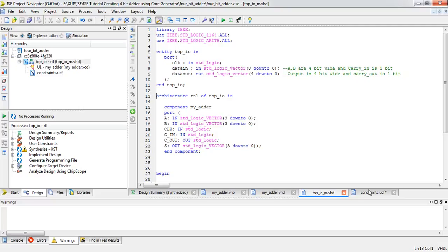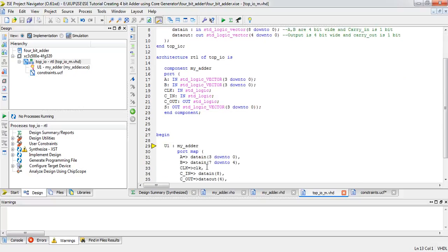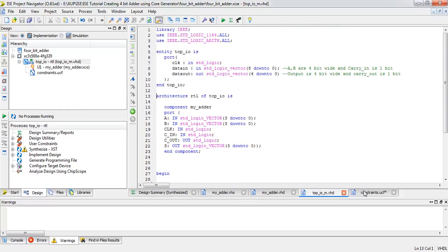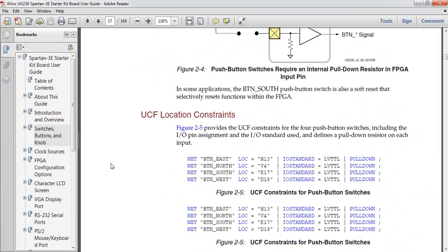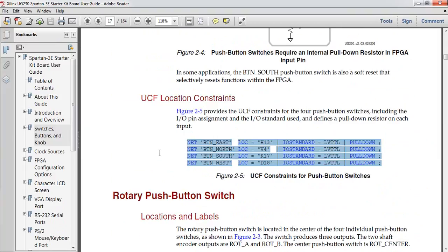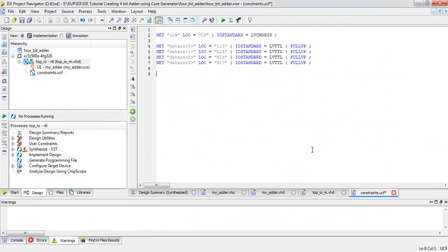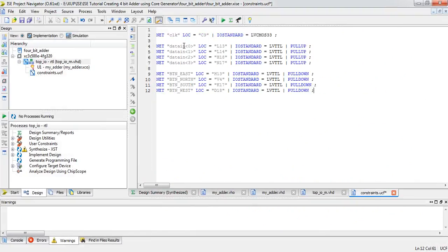So what we can do is we can just leave the carry bit. Carry bit is actually the 9th bit. So let's plan until the 8th bit. We are going to use these 4 switches also. Actually Spartan 3 has a very small number of general purpose input output pins. So if you have another board, you can plan according to that board.